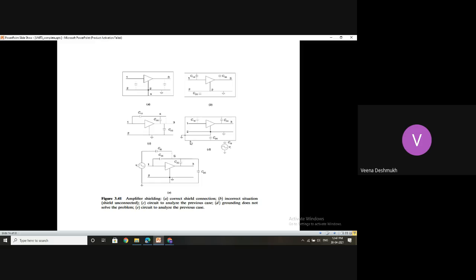This voltage, when it is produced, is going to again disturb the system. So if the circuit is big or if the shield is big, only one ground is not sufficient. Many grounds, which in turn are connected to one another to maintain common potential, have to be used. Now see the next circuit.